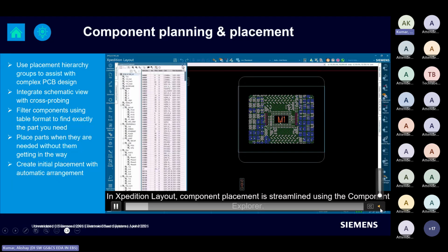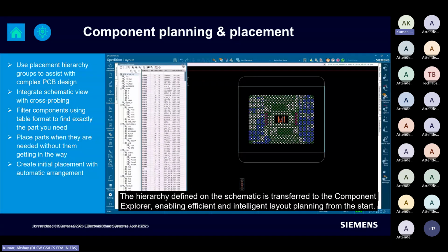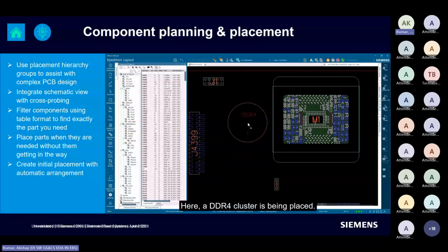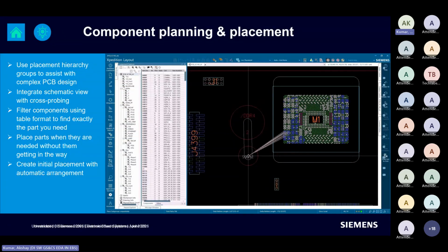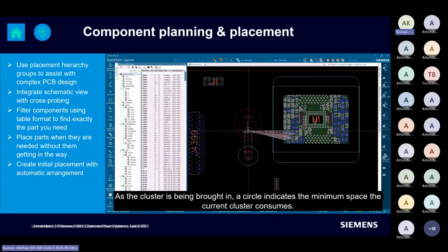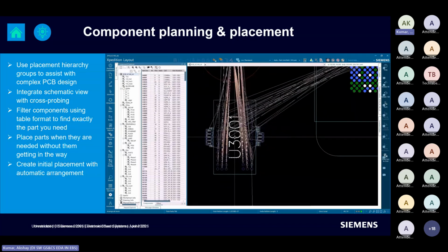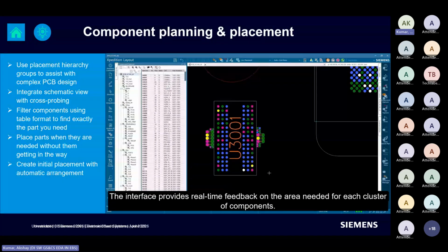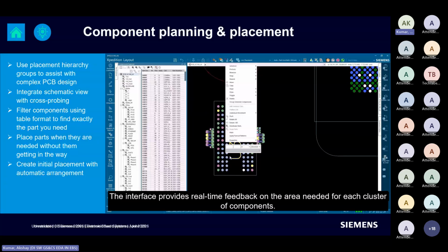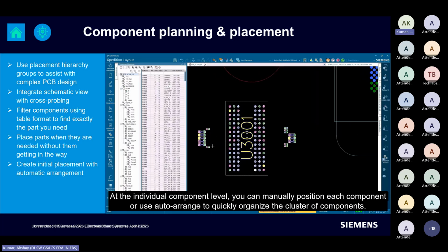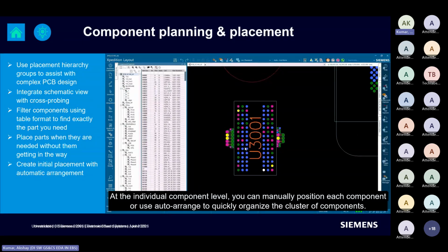is that you can have this grouping in terms of clusters formed in the schematic stage itself. So here itself, you will be able to reduce almost a week of time to just 5 minutes of work, right? You have a DDR circuit, which you can see here, getting placed in terms of a group itself. I'm not manually selecting any schematic or any component and extracting it, right? Instead, you can see almost 10 to 15 components getting grouped and coming together just when I'm placing on the board.